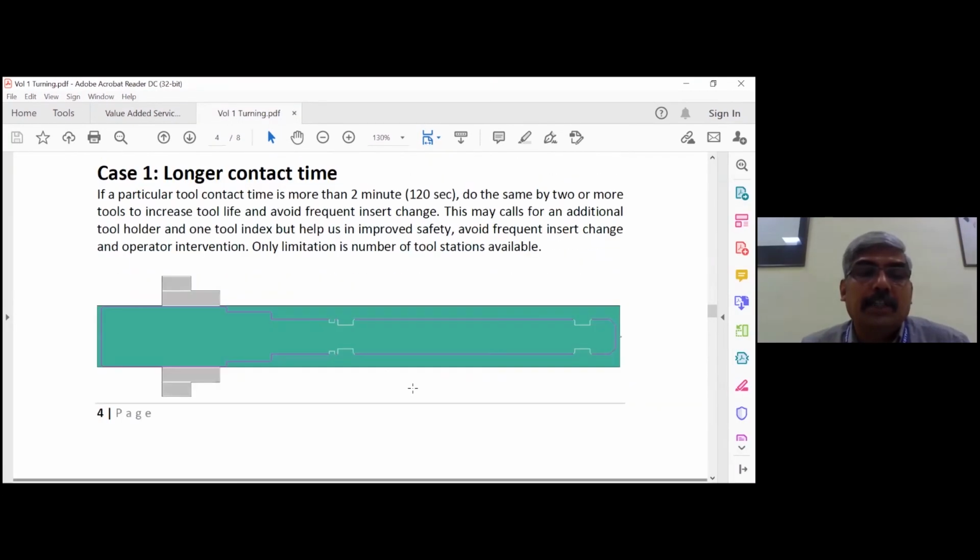See, this is an actual case study. This is a 30 or 31 dia input polished bar, with a length of 225 mm, and finally it will be turned down to a diameter of 12.7, half an inch. Then again there will be a groove here and a groove, and then one more groove, and the full length will have threading. The complete length there will be threading.